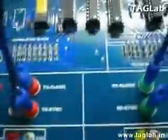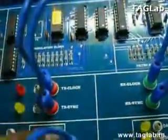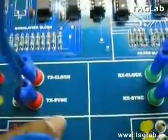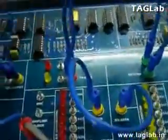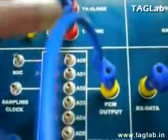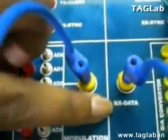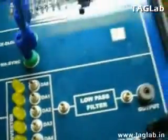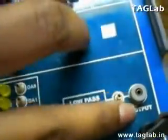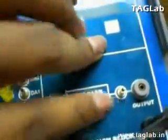Now here, firstly, you have to connect the transmitter clock to the receiver clock, and the transmitter sync signal to the receiver sync signal via patch cords. And to check the demodulated output, connect the PCM output to the receiver data mode of the PCM demodulator block, and you could observe the output of the PCM demodulated wave on the CRO.